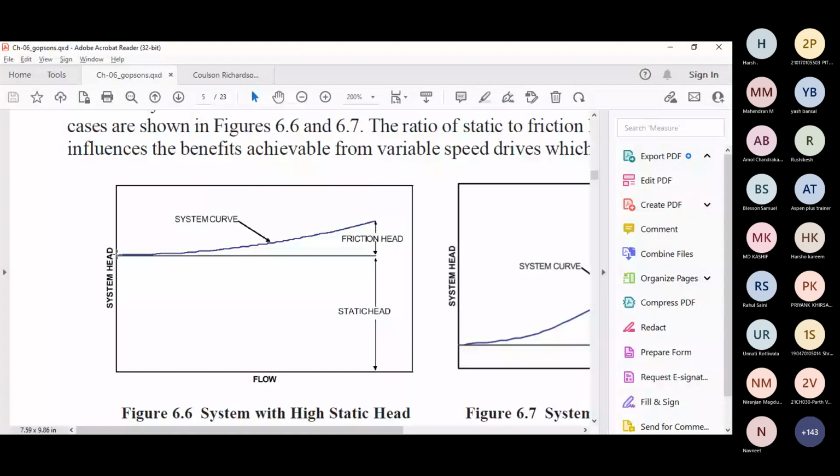And your system curve will generate some pressure. This pressure is because of the friction. So this is the pump system's curve, showing how your system is behaving. If you shut off the valve, it will be over here. The point at which your system curve intersects your pump curve is called the pump operation point.